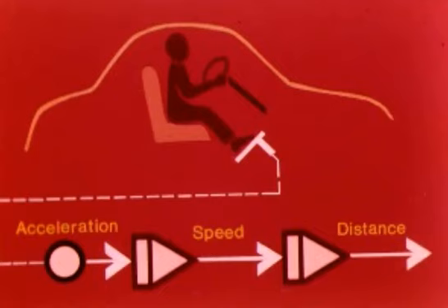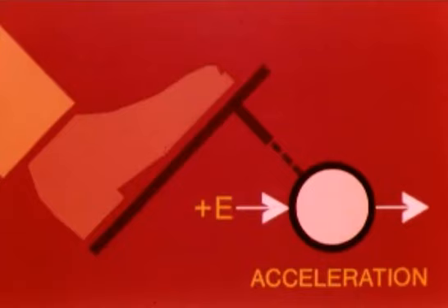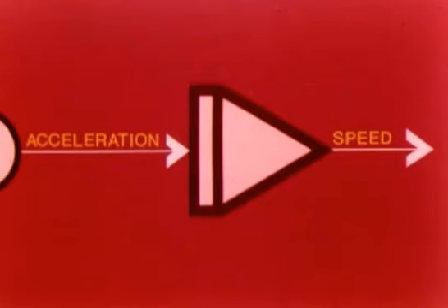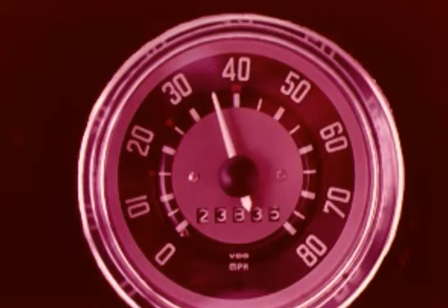This block diagram shows how several components could be connected together to simulate a trip that you might take by car. The accelerator pedal in this automobile simulator connects by a mechanical linkage to a potentiometer. The potentiometer output is a voltage proportional to acceleration. The acceleration voltage is the input to the first integrator. Its output is speed. The speed voltage could be connected to a speedometer display.